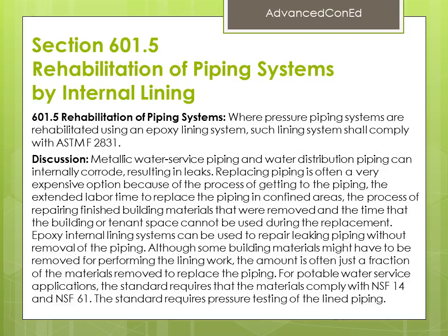Section 601.5 Rehabilitation of Piping Systems by Internal Lining. 601.5 Rehabilitation of Piping Systems. Where pressure piping systems are rehabilitated using an epoxy lining system, such lining system shall comply with ASTM F2831.